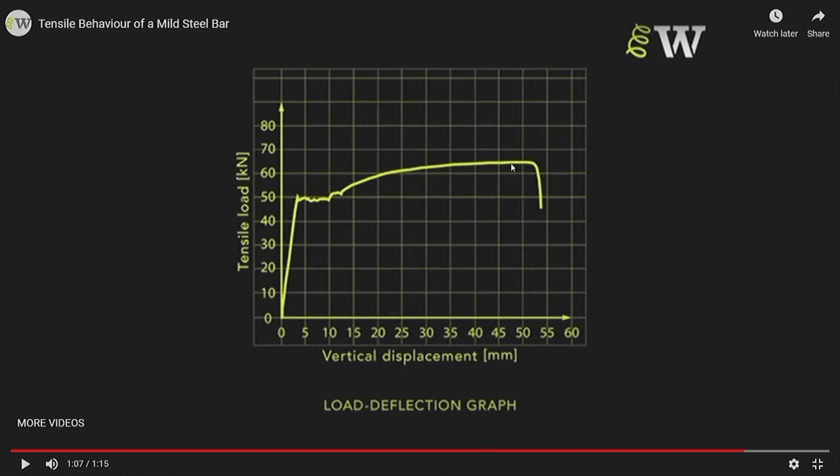So that is about here. It increases for this specimen about 10% of its length before it finally fractures. So that often gives people enough warning when a mild steel specimen is likely to fail. And this behavior is called ductility or ductile behavior. Not all specimens are like this. Some of them fail very quickly without much of a warning. They are called brittle material.